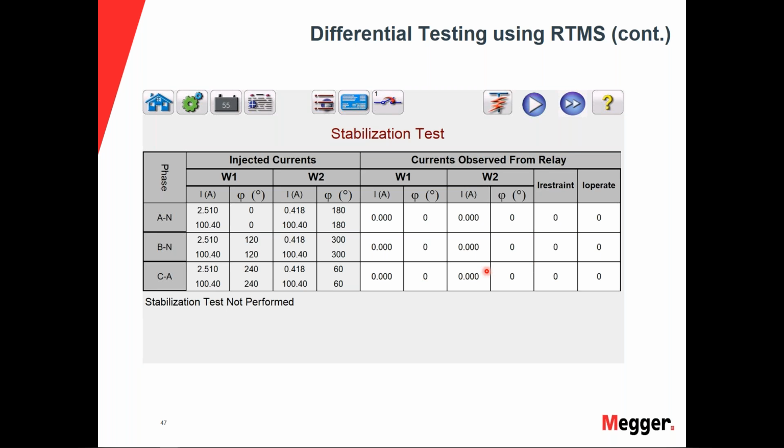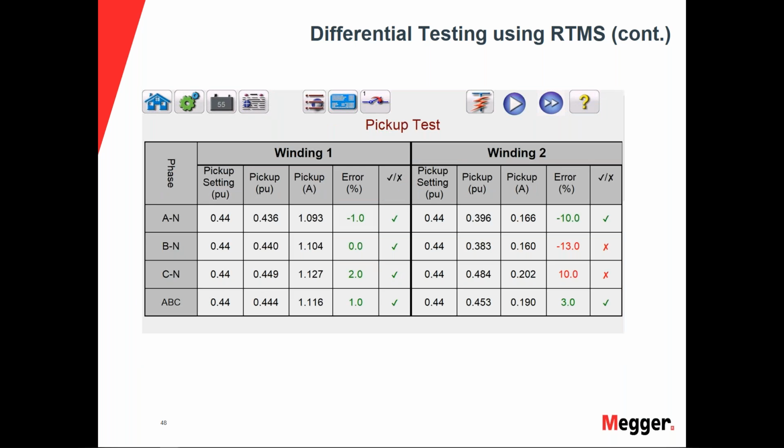That will validate our connections, that will validate our leads are proper, that will validate that we have good equipment and everything is working properly. So it is a good test to run. It's always a good test to run at the very beginning as well. We'll do our pickup test.